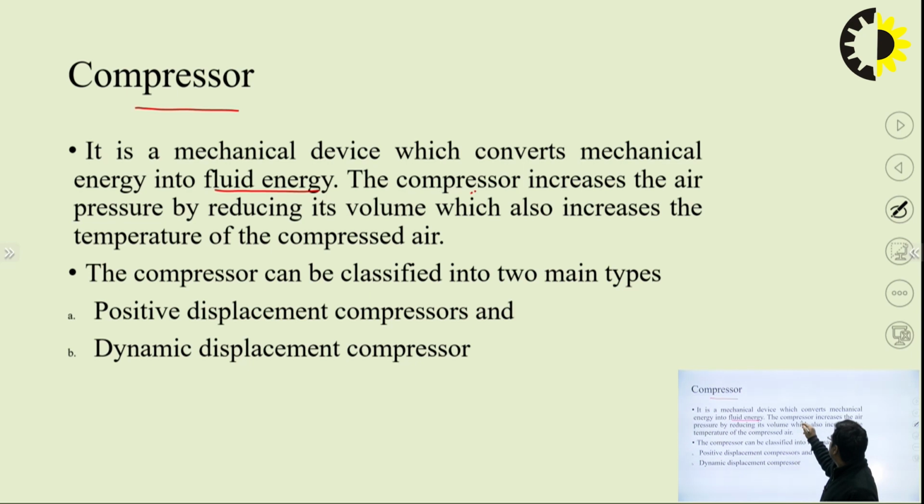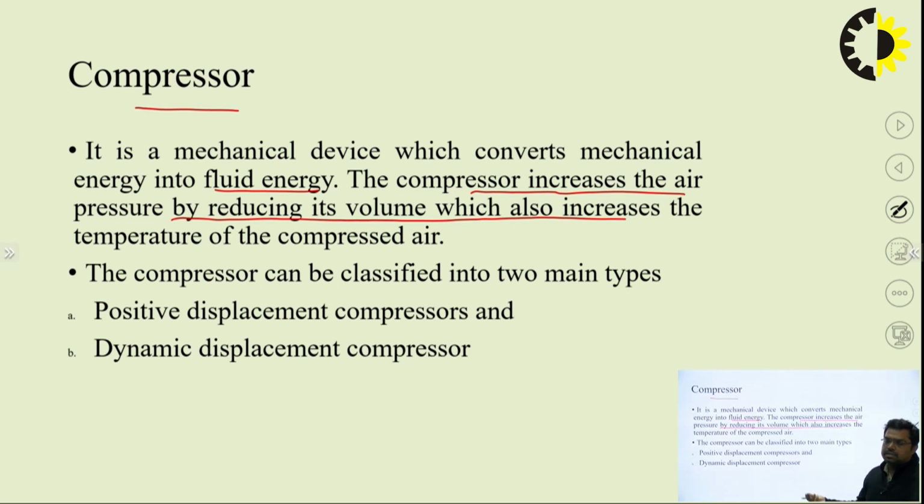The compressor increases the air pressure by reducing its volume, as discussed in Boyle's law and Charles's law, and this also increases the temperature of the compressed gas.